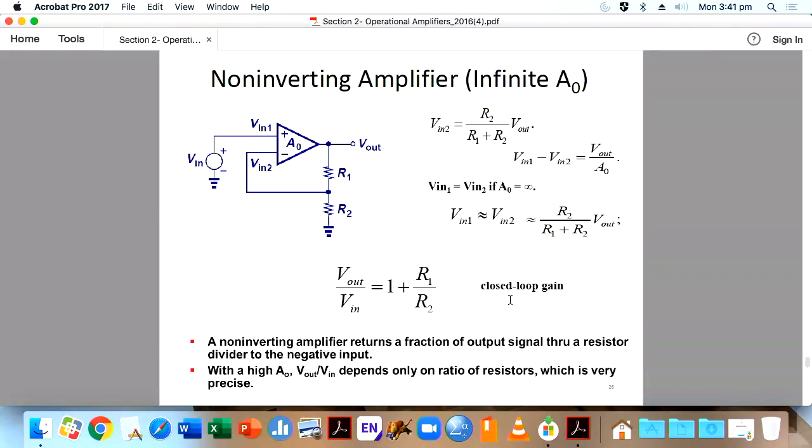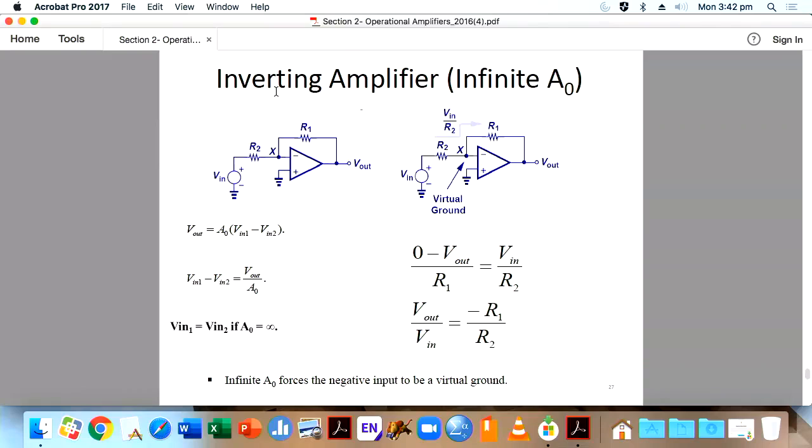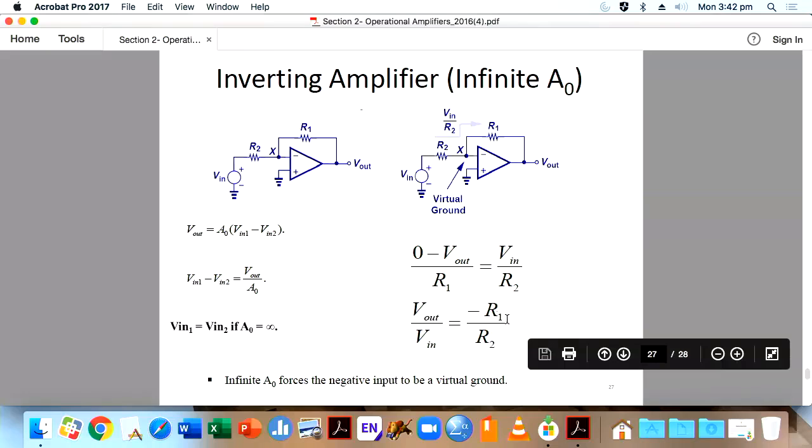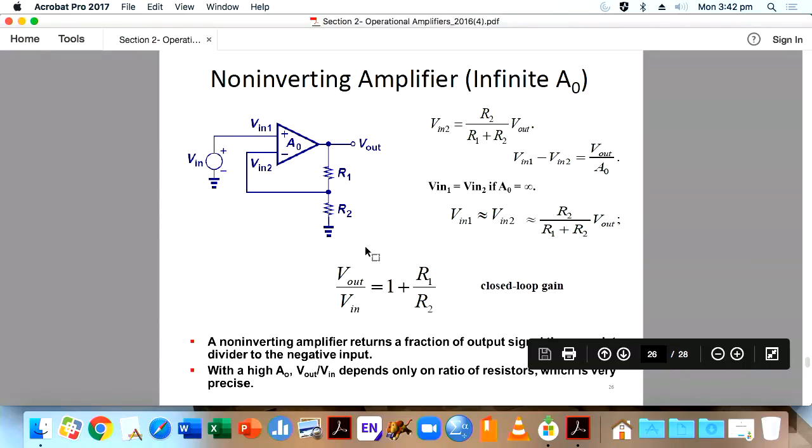Okay, so somebody designed this one. So now you have been hearing about non-inverting and inverting. Somebody designed a non-inverting amplifier, then somebody designed the inverting amplifier. Forget about the phase shift, because here you will be getting a phase shift, meaning the signal will be inverted here. And the gain is almost the same, in the sense R1 by R2. Here it is 1 plus R1 by R2, only 1 point difference.